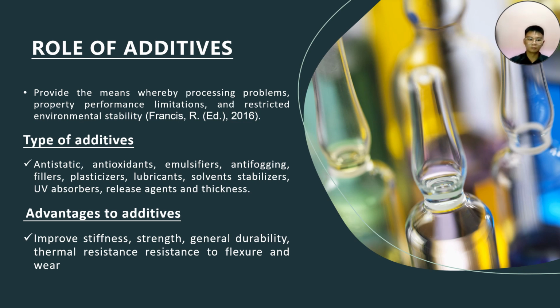There are several types of additives. First is anti-static, antioxidant, emulsifier, anti-fogging, filler, plasticizer, lubricant, solvent stabilizer, UV absorbers, and release agent, as well as thickness. The advantages of additives are to improve the stiffness, strength, general durability, and thermal resistance.